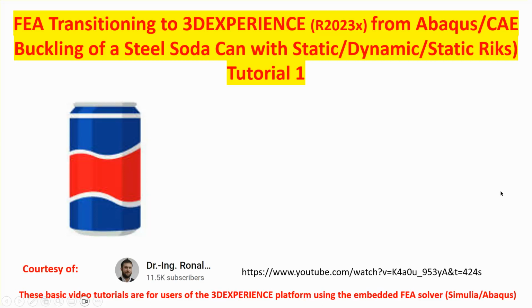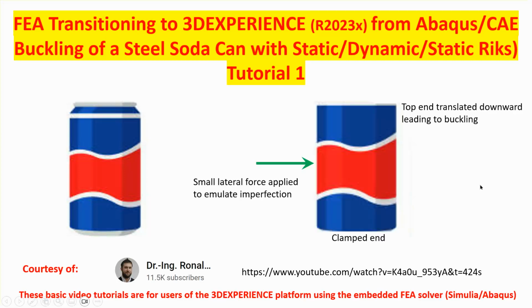I do, however, make a simplification here, and that is I assume that this is a straight cylinder without the top and the bottom indentations, and the bottom is clamped and the top is being pushed down by a certain amount. And in order to mimic the concept of imperfection, this YouTuber is applying a very small lateral force at a middle location. So that's the way he brings imperfection to the picture.